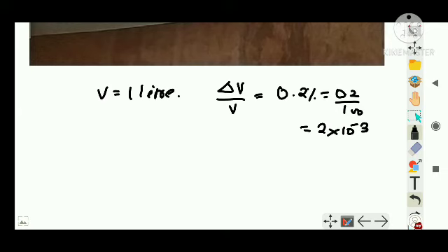So bulk modulus, I hope you remember, is equal to force per unit area by change in volume by volume, and there is a negative sign. If you don't require the negative sign, it's okay. In place of force per unit area, here I will write pressure. That also I have taught you, right? Or I can write this as PV by delta V, right?